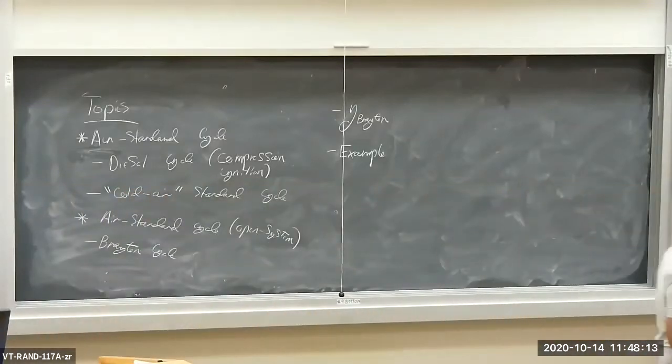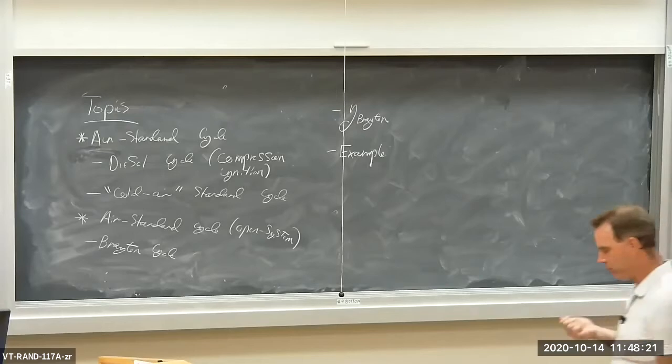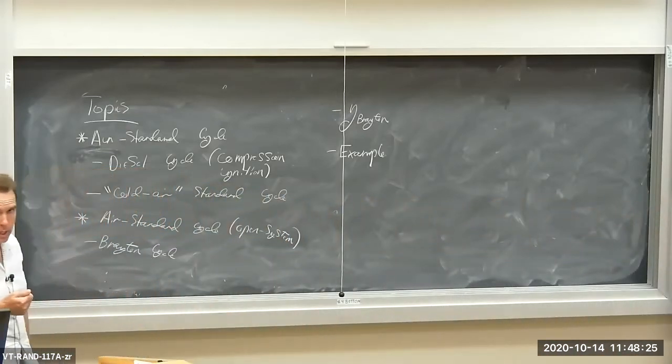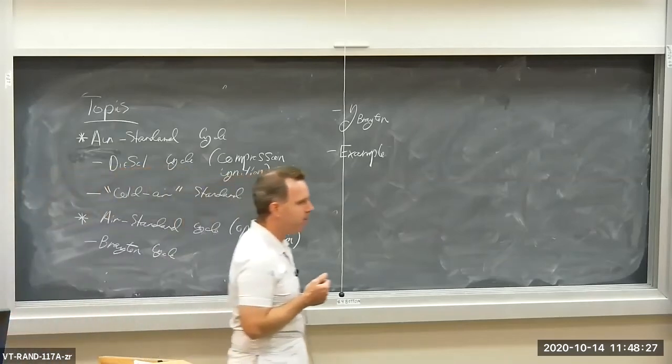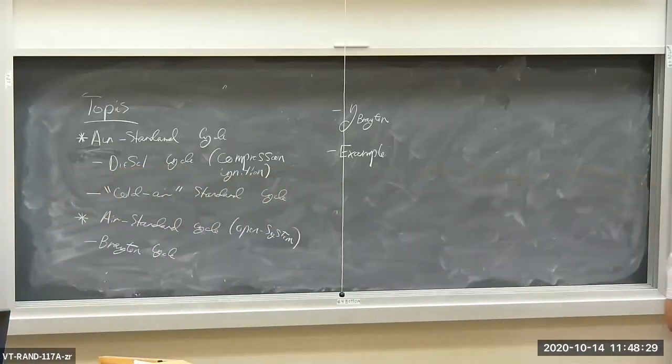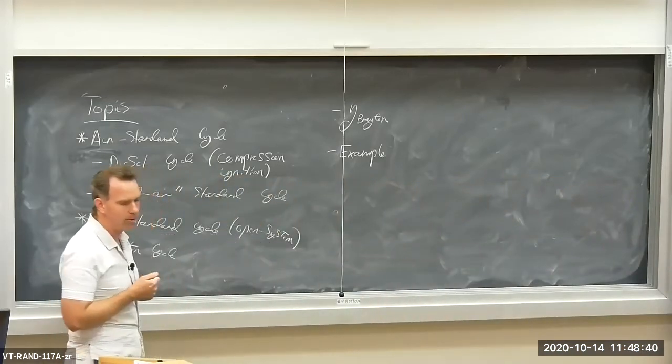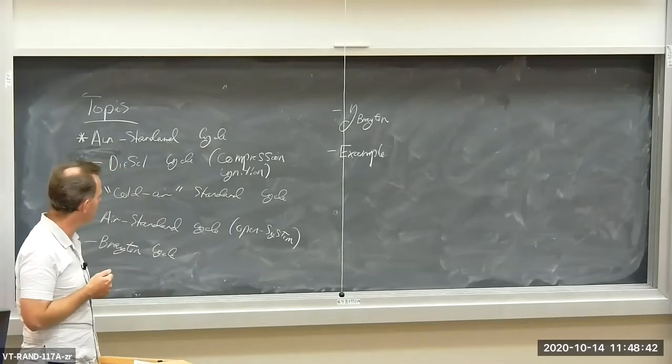So today we're going to continue on and look at another cycle. We've looked at the air standard cycle analysis, we looked at an arbitrary cycle, an example. We did some detailed numerical calculations. We looked at the Otto cycle, which is a representation of a spark ignition cycle, primarily gasoline. The Otto cycle mimics the gasoline engine as far as blackboard thermodynamic work is concerned.